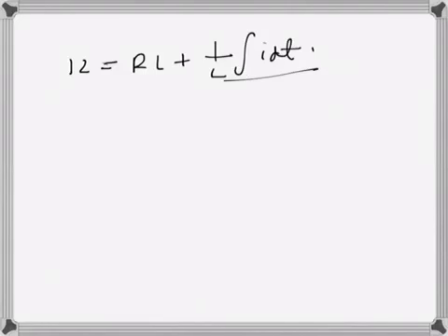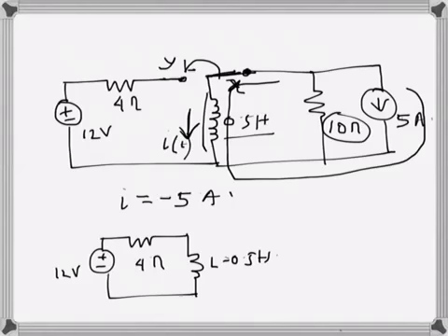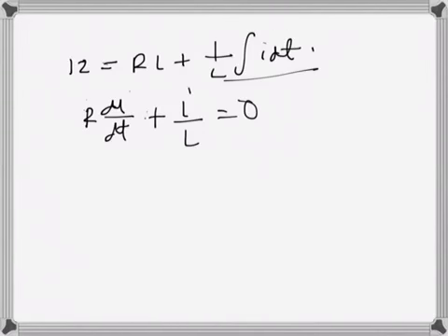The current through an inductor cannot change instantaneously, we know that. So this is becoming di dt plus IL. So we can see from this that finally the inductor will again be short circuited, and the final current will of course be defined by the voltage source and the resistance, so that will be 3 ampere. So if we say I final, that will be 3 ampere.